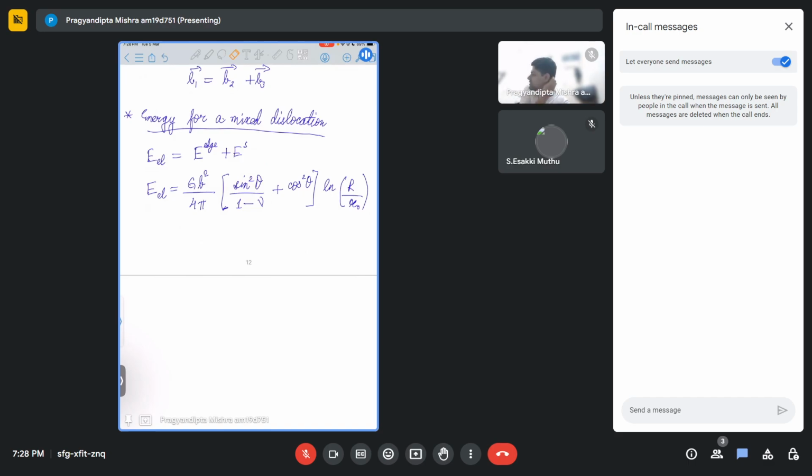Essentially, what is dislocation trying to do? It is trying to manifest the energy present within the structure. Now, this energy could be present at different spots, right? That will lead to bowing of a dislocation. However, a dislocation will always try to be in a straight line, right? Because bowing will cost an extra amount of energy.